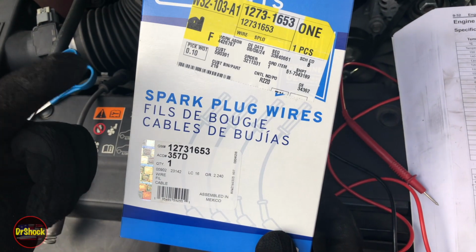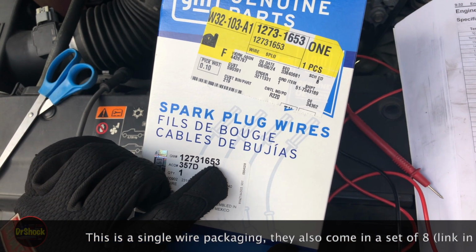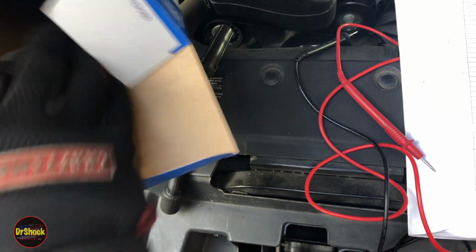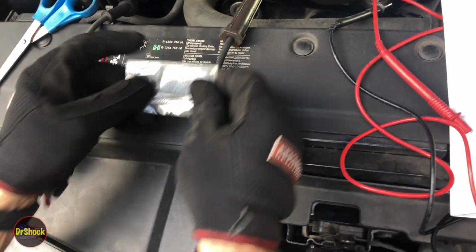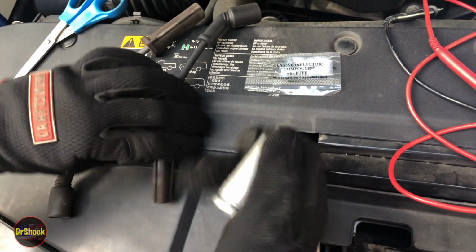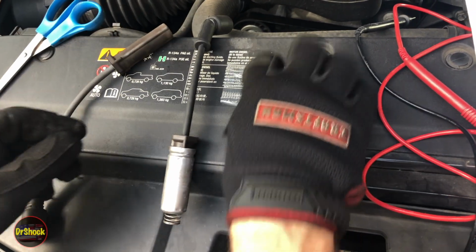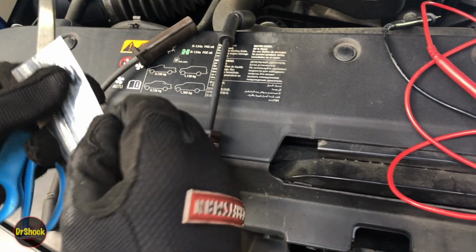All right, guys, so this is what a GM ignition plug wire for this engine is going to be. A GM 1273, 1653, or an AC Delco 357D. Big box. You just get a new one of these and a little packet of dielectric grease, because that's a mandatory thing to be using. So we'll need to take our old heat shield off and put that on our new plug, right? And then we'll just cut the corner off of our dielectric.